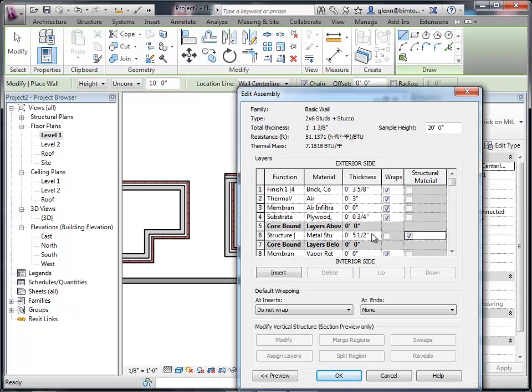You're going to get used to the idea that 2x4s are 3.5, 2x8s are 7.25, 7.5. 2x10s are definitely 9.25. It drops off in weird ways. And I defy someone to explain the logic behind it. But okay, we have metal studs right now, 5.5. Well, 5.5, that's pretty good. Metal studs, though, not sounding right.